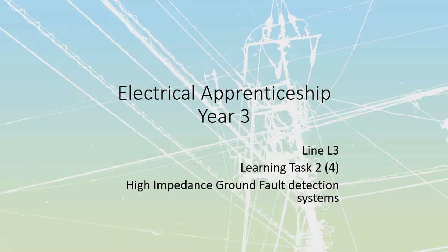But no matter what it is, the Canadian Electrical Code will class them all together. You can go into Appendix B to take a look at the note on Rule 10302. It does require that we have a protection and control, or what we call a P&C system, for their operation. Specifically, we have to monitor for the following faults, and there's a list inside of your table, or outside of page 38.